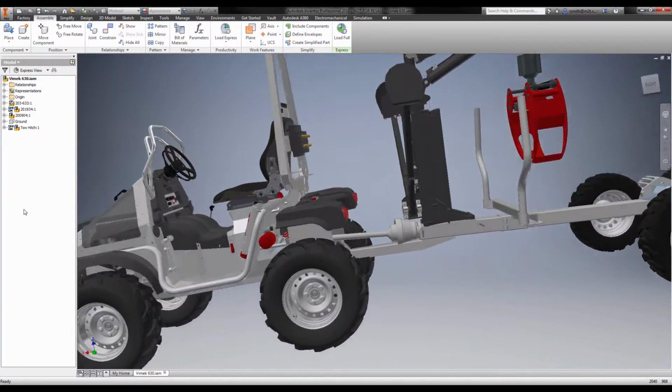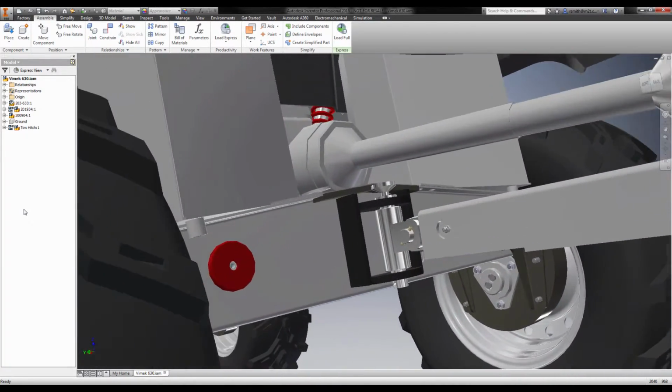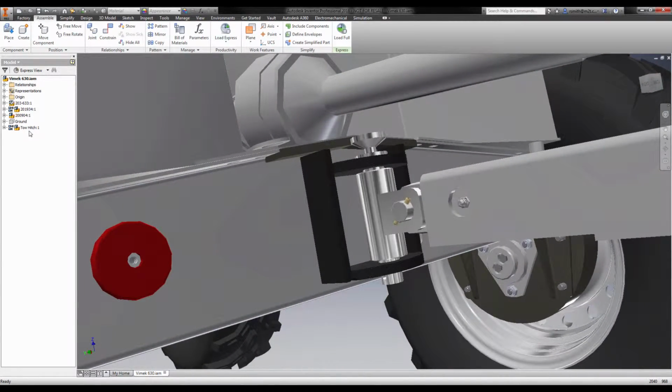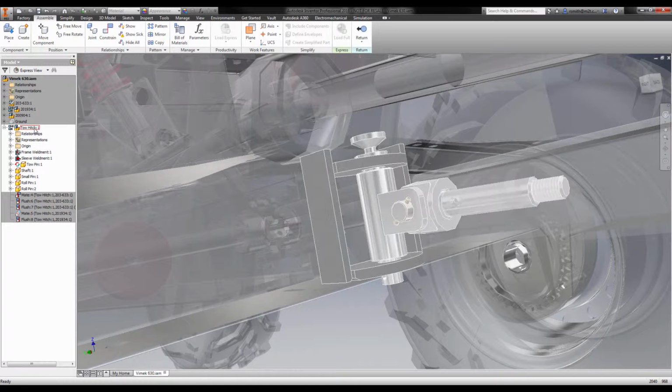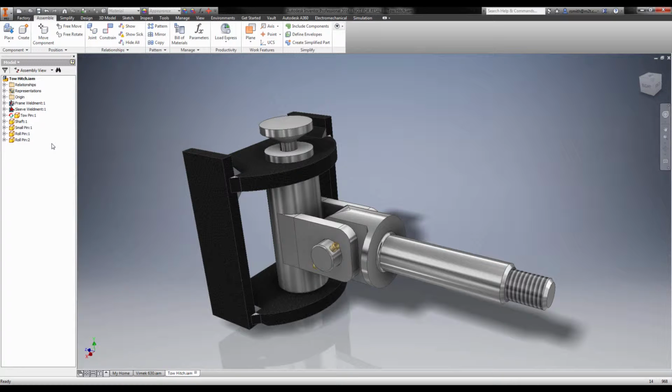Finding the right balance between mesh complexity and the accuracy of results is a common challenge in simulation. Removing solid geometry from the problem reduces the amount of elements that need to be created. This can reduce solve times, or the extra resources you have gained can be spent on a finer mesh without increasing solve times.